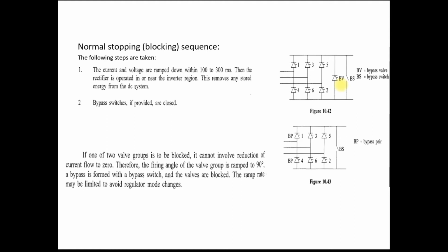In some instances, the blocking of the valve at the inverter side creates continuous conduction through the previously conducting phase, placing the AC voltage on the DC side and the direct current on the converter transformer. Because of that, to protect against this high voltage, we require the bypass valve as well as the bypass switch. Therefore it is necessary to bypass the bridge when the valves are blocked.